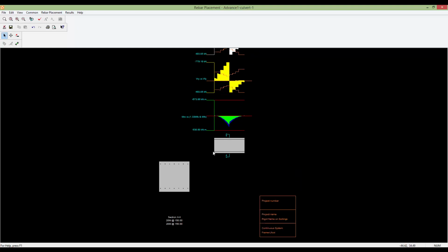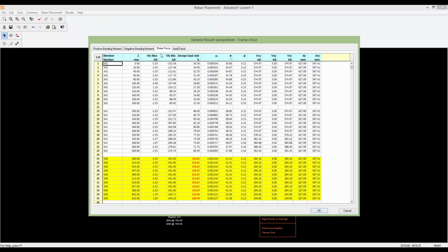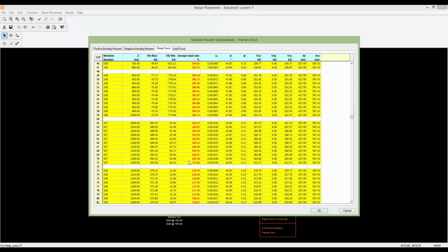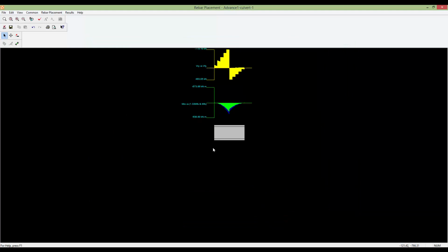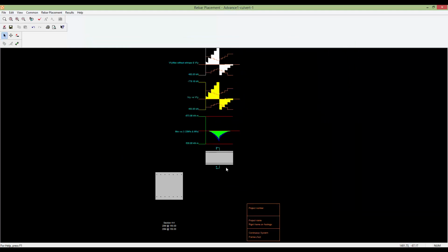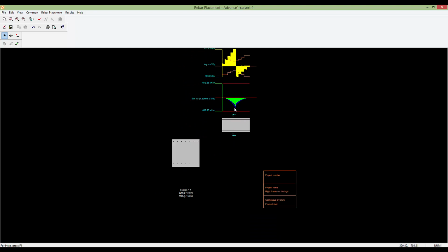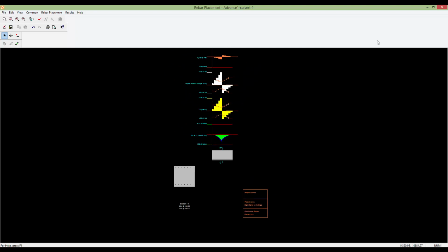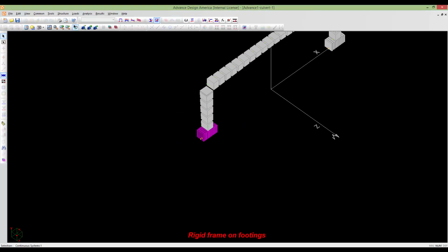I will have the slab, we may have some problems with shear. If I check the results for shear, yes. And as I already explained to you, you can add the extra stirrups here to make the foundation stronger against the shear force.